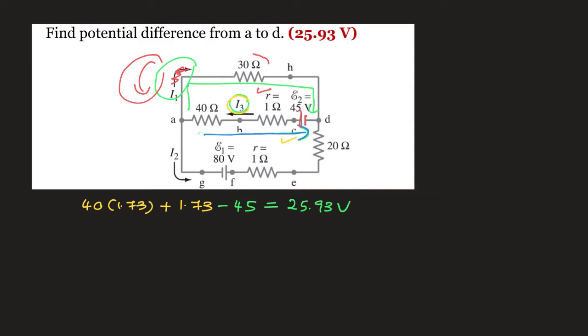And there's no more resistor or battery here, therefore the 30 ohms multiplied with the answer from I1, which is 0.86, is going to be equal to 25.8 volt. You don't have to be worried because the difference is around 0.01% or 0.1%. It doesn't affect so much, and both answers are still accepted. So it means that the answers you get for I1, I2 and I3 are correct. If you want to check whether your I2 path gives the same potential difference, you can do that, but still you are going to get the same answer.